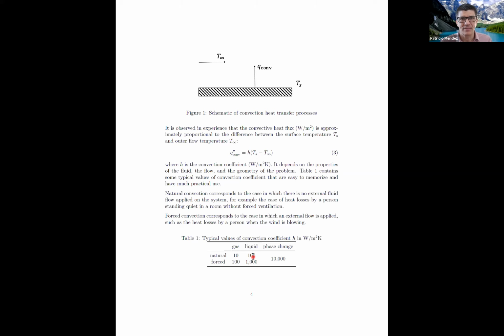What happens is, as I'm sitting in this room and losing heat at 10 watts per meter square Kelvin, my metabolism is perfectly balanced with that. Happy person. If I were to take a dive now and start swimming in water at 20 degrees, I would be losing 100 times that amount of heat, way more than my metabolic heat.